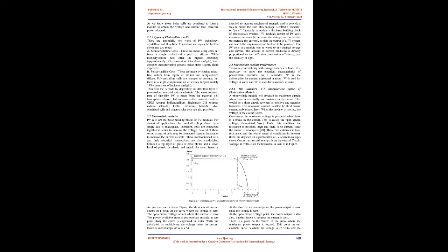Jinhui Shui, Zhongdong Yin, Kipeng Song, and Renzhong Shan [12] presented a paper about the analysis and research of the inverter for a grid-connecting photovoltaic system. In their paper they described the topology of the main circuit, control methods, and design of the passive filter. The important point of their paper was control methods for grid connecting, PFC, and control methods of power direction. Based on analyzing the SPWM, sinusoidal pulse width modulated, technique control method in detail, this paper improves the control means. This paper proposes a neoteric grid-connecting inverter, which synchronizes a sinusoidal AC output current with the utility line voltage, and controls the power generation of each photovoltaic battery cell.